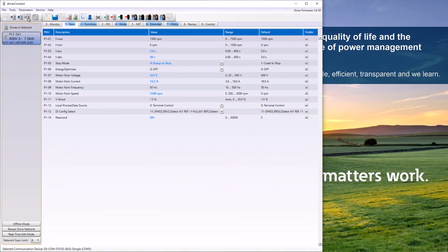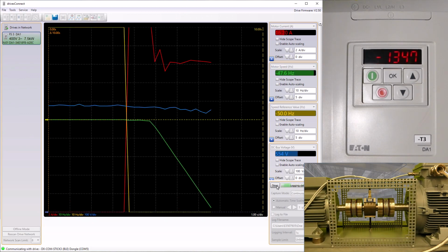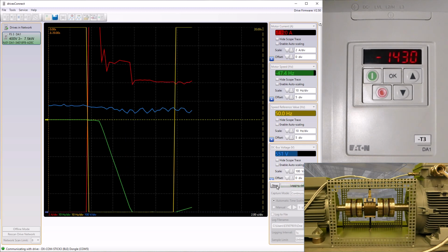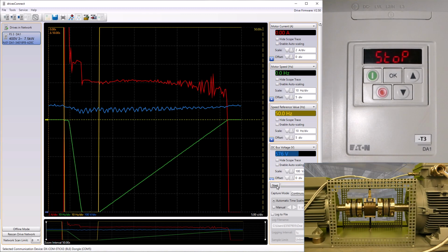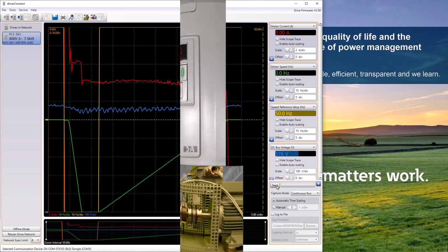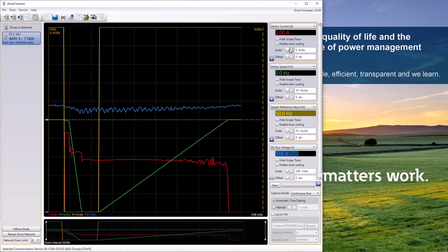Due to the short ramp time, the DA1 enters the overload range with approximately 21 amp, which is indicated with dots in the display. At the reference speed reached and during the subsequent slow deceleration, the DA1 runs with the rated motor current of 14.2 amp. Due to a too small selected scaling of 2 amps per div, the recorded motor current exceeds the maximum displayable range of 10 div. Here no recording with new scaling is necessary, but the original value is corrected to 5 amp per div.